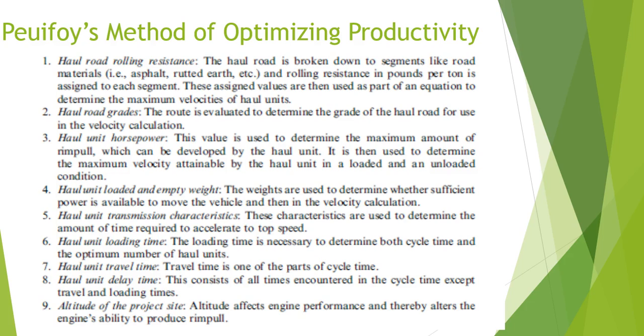Now, the loader itself also would have a cycle time. The loader will be by the truck, then the loader is going to move to the pile that it's filling. It'll fill the bucket, back up, go back to the truck, empty its load, and then the cycle will start again. One last factor that Purifoy considers is altitude, and altitude affects performance.